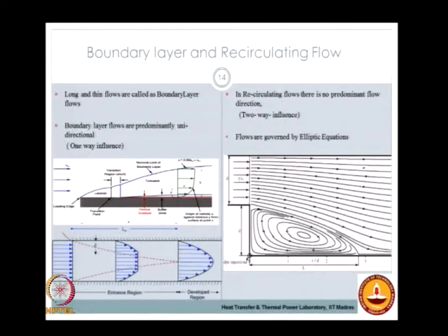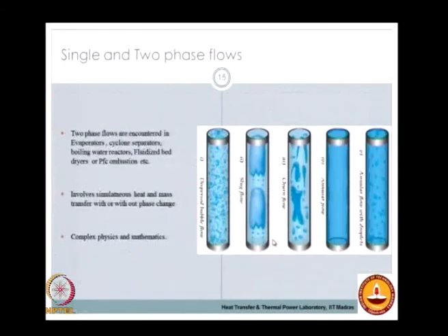corner here. So if you look at two kinds of wall bounded flows, one is where your boundary layer theory can be used, such as in this case, and the other is the recirculating case, where the boundary layer loses meaning once the flow separates and recirculates.